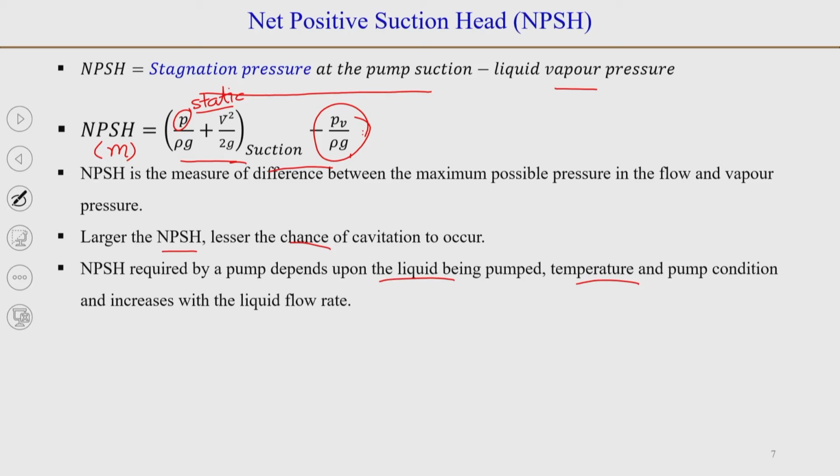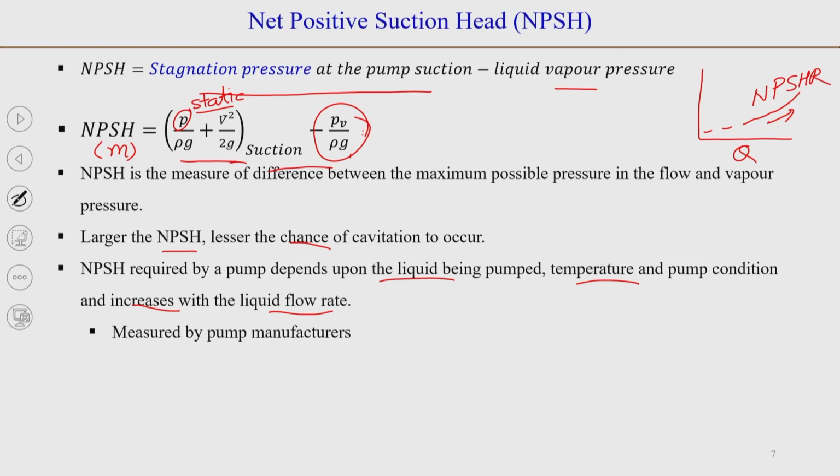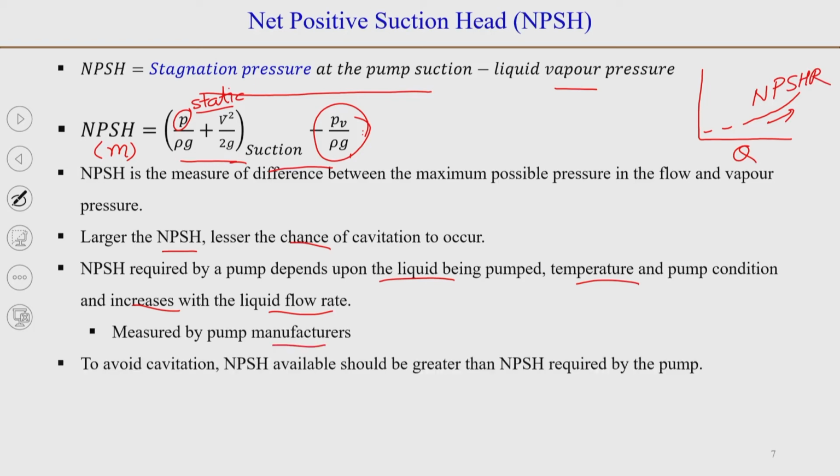It will also depend on the liquid flow rate, and this required NPSH will increase with the flow rate. This will be provided by the pump manufacturer.